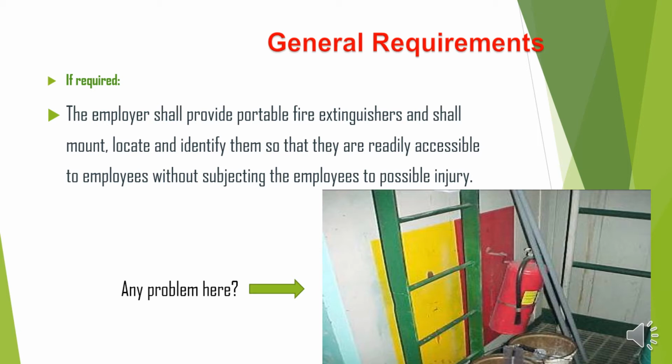As I said before, we have to enumerate them, know the location of them. The location must be correct according to the practice guidelines or according to the rules of the civil defense. How many, what kind, where I have to put them, and we have to inspect them periodically, and we have to test them periodically. From this picture, if there is any problem, you can see it. I'll give you 15 seconds. If there is any problem here with the fire extinguishers, particularly,